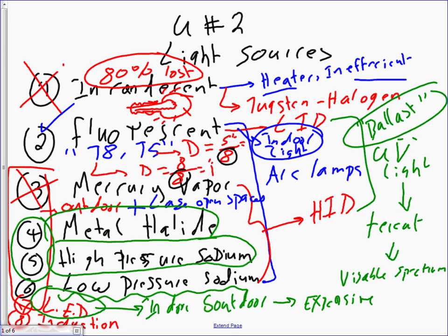Let's move into the other one. So we have low intensity discharge. The fluorescent is called an arc fixture with low intensity discharge. The discharge current is low. Then the other three guys, 1, 2, 3, are also arc lamps, but they have high intensity discharge. The arc is a bigger arc. So, smarter than Chad said, what if we want a bigger arc? Then they created the metal halide.